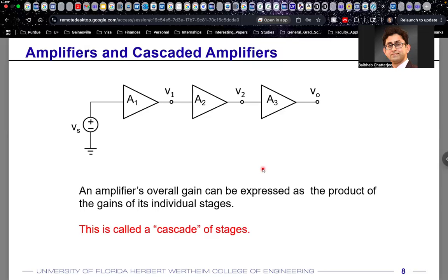That if your input is a sine wave, your output should also look like a sine wave. That means there is a 1:1 correspondence. The voltage at this point multiplied by 5 becomes the voltage at this point, the voltage at this point multiplied by 5 becomes the voltage at this point, and so on. So your output is directly A multiplied with the input.